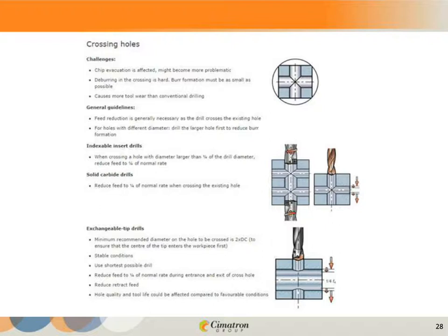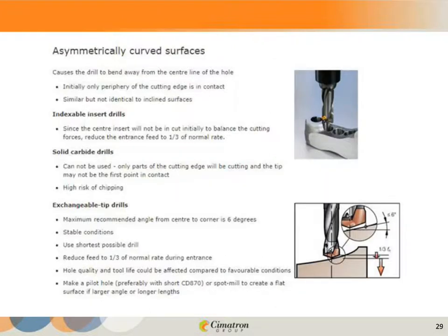And here, of course, if you're trying to drill on an asymmetrical surface, it's going to require machining like we discussed earlier. Although I think in this picture, if the angle is enough to not obstruct the flute and the drill is stubby enough, probably you can get away with a situation like this. Again, it's very specific to the application.